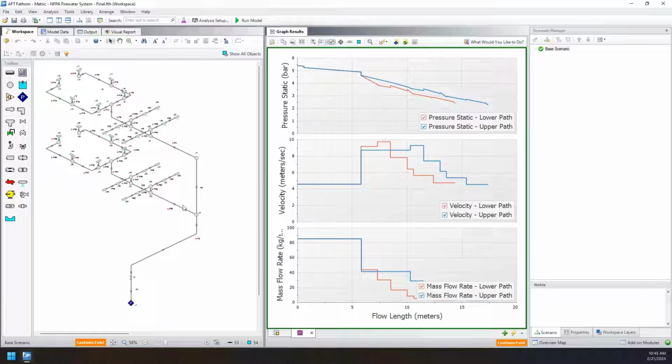So remember, in this system, we put these side by side. We have all of this flow going through a main line, and we have these draws off our header going to these different sprays. And every time we have a draw, every time we have this reduction in mass flow rate, depending on the size of the pipe, we might increase or we might decrease our velocity. More often, when we remove flow, we have less mass flowing through the same area, we see a reduction in velocity.